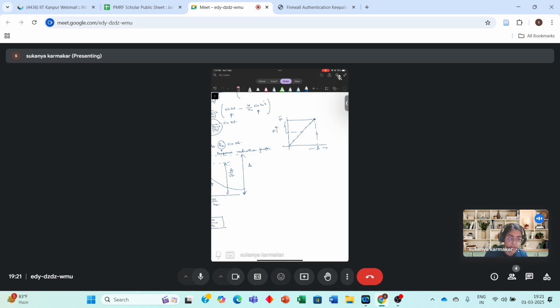Now I don't want my structure to be linear elastic. I accept the fact that there will be a certain damage, and my structure can take that damage. Because of that, in concrete we do ductile detailing, and we reduce the force by a certain factor R. Because of that, the deformation in the structure increases, but it can take it. So this is that response reduction factor, which is there in the book.